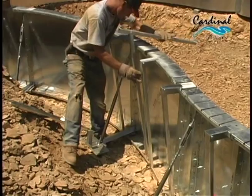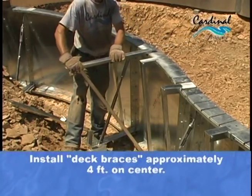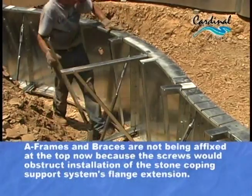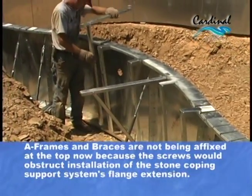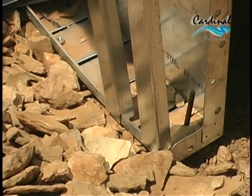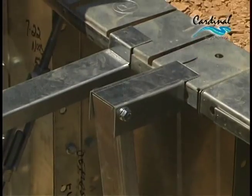Deck braces are installed in a similar fashion. Install deck braces approximately 4 feet on center. Notice how once the vertical support is placed over the flange, the notched piece bends during installation. Remember, this assembly is embedded in concrete when the collar is poured.